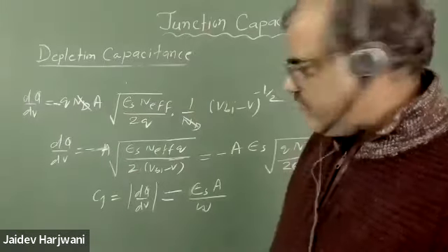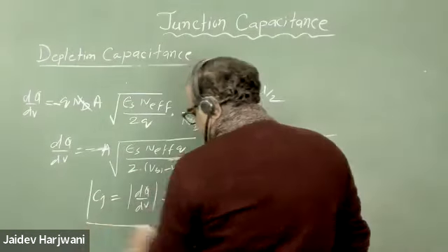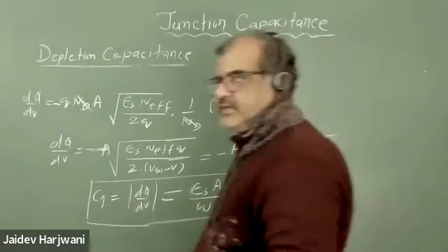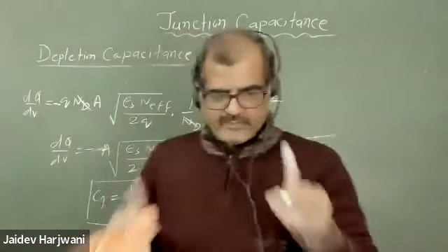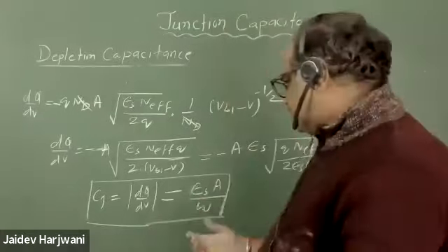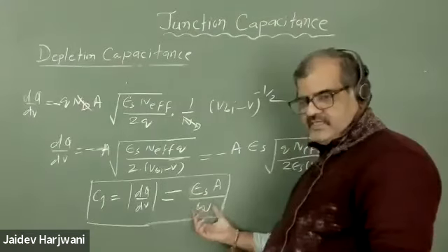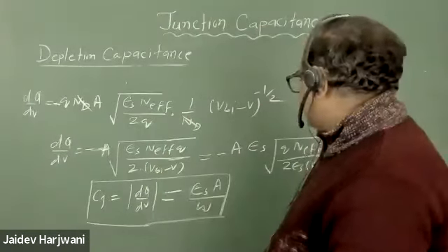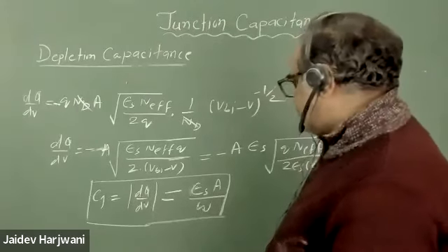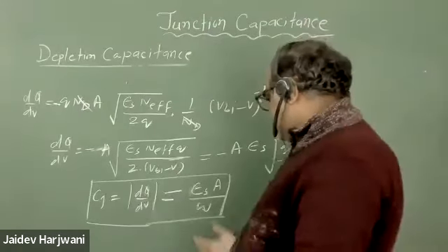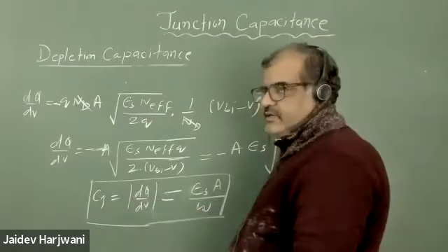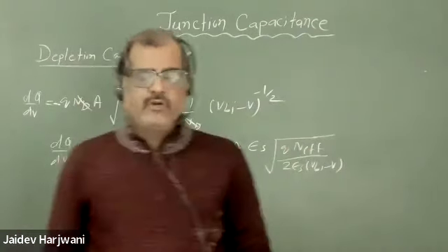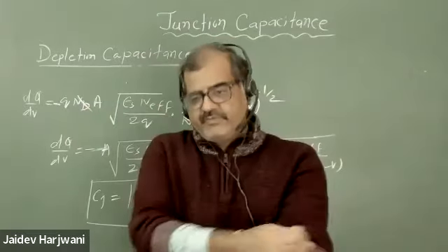That's why it's giving a capacitance behavior, like a conventional capacitor where you have 2 plates and you have a width. So here the distance d between the plates is equal to W, and you have charge separation at this distance. Now if we do a little bit more, by measuring this capacitance value in the laboratory, we can measure the doping profile, and know how much concentration we have doped in our PN junction.